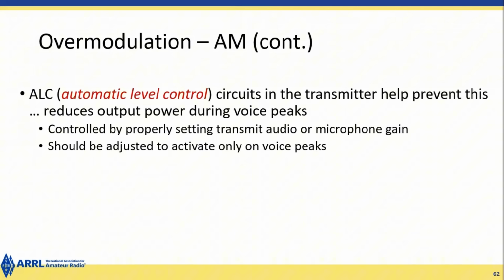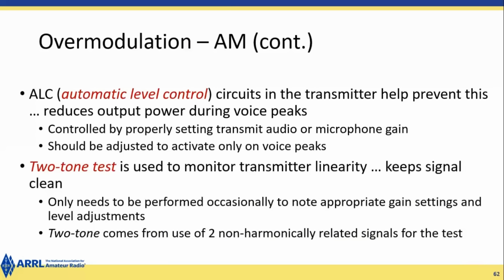A two-tone test is used to monitor transmitter linearity, which keeps the signal clean. It only needs to be performed occasionally to note appropriate gain settings and level adjustments. Two-tone comes from the use of two non-harmonically related signals for the test.